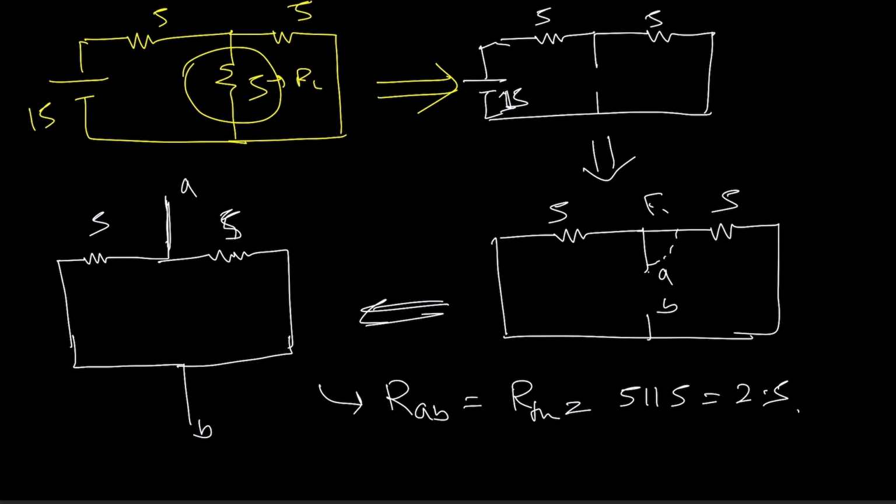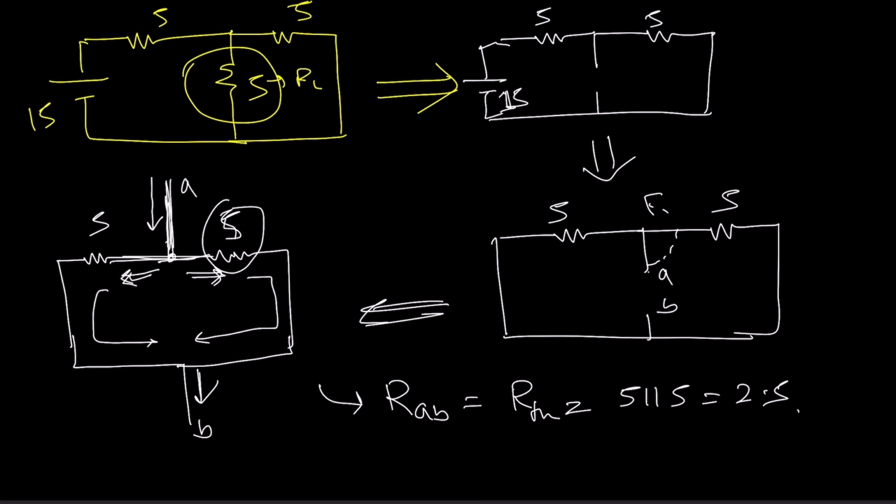Whenever you need to calculate the equivalent resistance, parallel or series, what you need to do is think of this as a pipe, okay, and then this is another two pipes. That means suppose you flow some water from here, then this water divides into this side and this side, right, and then this water will flow this way and this way, and then it will meet again and go from this side. Whenever water divides at a node and goes with separate branches, these two particular branches will be in parallel, okay. Like if I show you just an example,